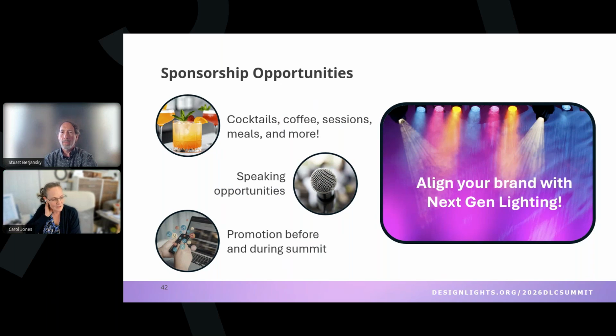Yeah, so the straight up answer is that it depends on what you want out of your lighting system. If you want accurate energy reporting, then you're not going to get it from 0 to 10. Full stop. You just won't. If you want linear dimming, you won't get it from 0 to 10. If you want information beyond the circuit-based measurements, which sometimes includes other load or from the building, you're not going to get accuracy as well. And if you want to have connection to other building systems, that's necessary to have. It can be anything from an occupancy technology that is a platform in and of itself. So all of the features that are discussed here, it depends on if your project wants to have those features.